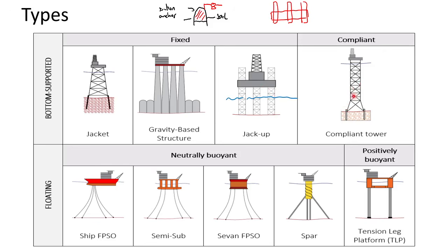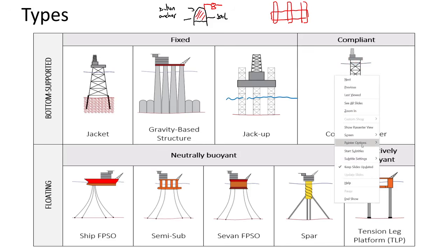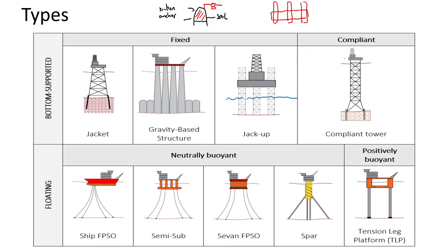And then you have another type of structure that in this case is different than the jacket, but is a similar approach, but these are for deeper water levels. And this has the same cross section, because to make a cross section like that, you will need a base that is very, very big. So you have the same cross section, and you have some movement. Due to that, you have some movement in this direction. So what you typically use in this structure is that you put some tethers, just fix it with some cables to the soil, to the seabed.